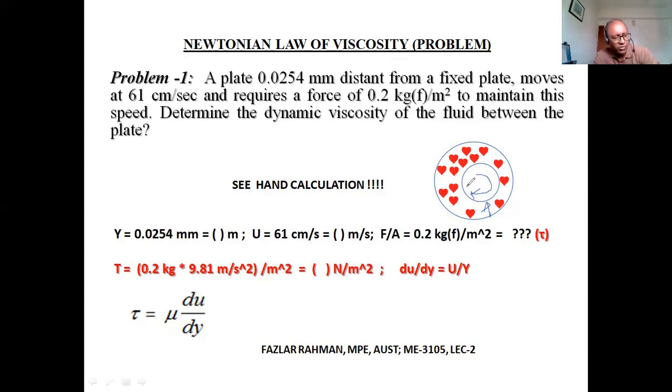So you need to make sure that you are using the right amount of the right type of fluid. For example, if you have a car or truck, you have a differential gear in the rear axle. They have a specific fluid. If you use a higher, denser fluid, then what will happen? Your bearing will be damaged. Same thing with engine oil. The manufacturer has a recommendation of the specification of the engine oil you use in your bike or in your automobile engine.